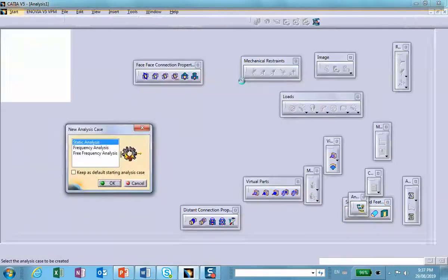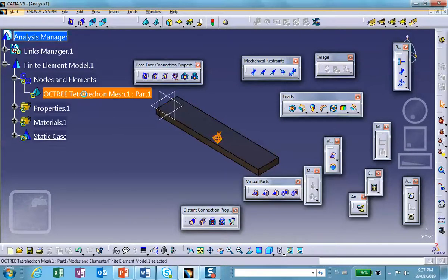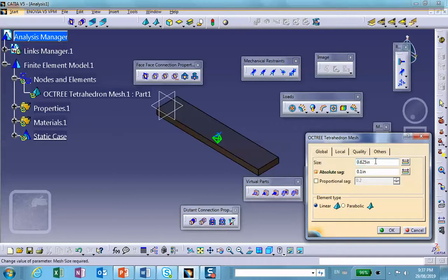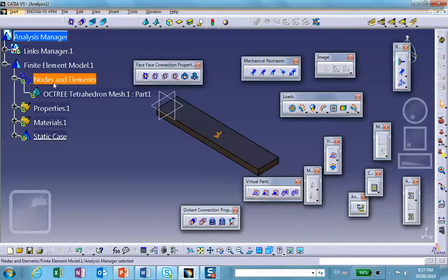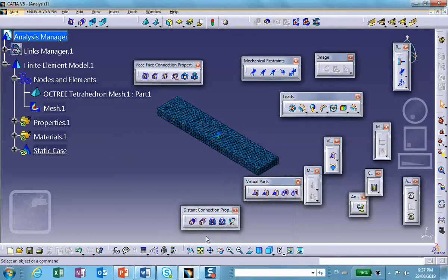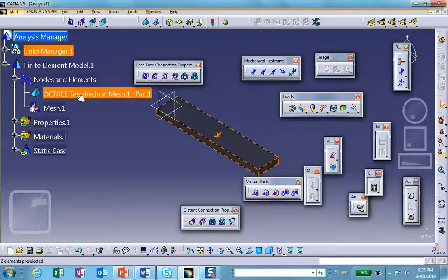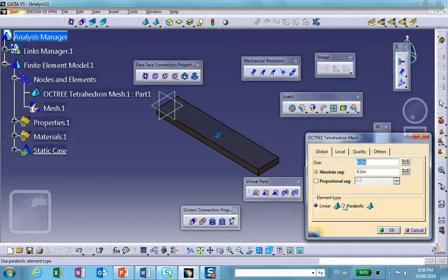Okay, just so that things are not too ugly, let me go ahead and change the size here to point maybe 2. Let's see how it looks like. Okay, so it looks like that. So if you mesh, it will be relatively fine mesh. Okay, so let's deactivate this. The other thing is that, as you are aware of, when I use parabolic elements, the displacements don't always come out right as far as the shaded contour because of my graphics card. All right, so let's move on.